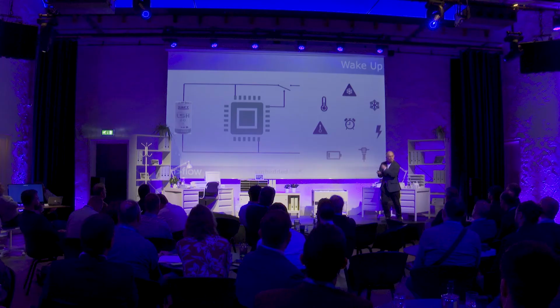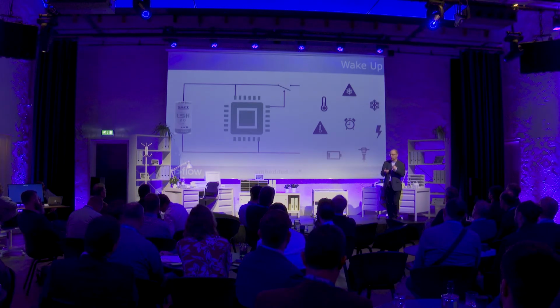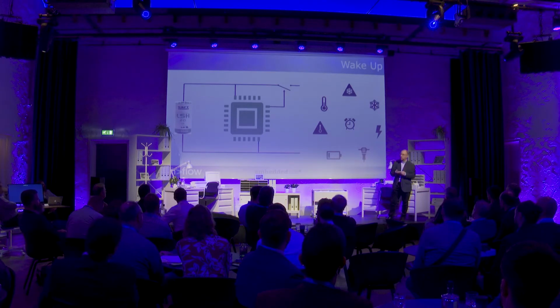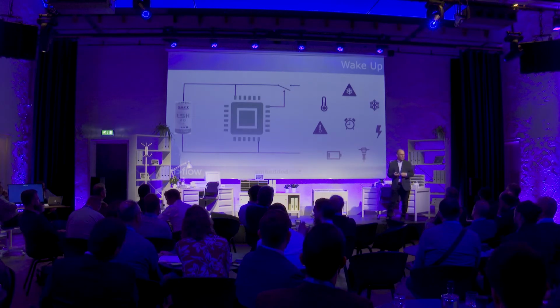If we're going to switch power off to the radio modules, we need to consider how we're going to wake up the system, how we're going to turn those modules back on again. And there can be many triggers in our embedded systems to wake up. I show some here. Hopefully we can wake up from a low battery alert. Hopefully we can wake up with a temperature change or when a fault condition occurs.